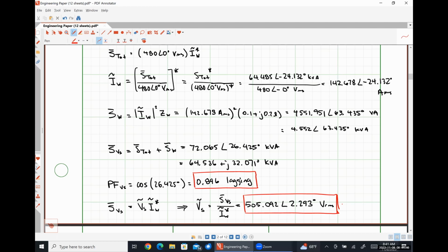So an electric utility prefers that we operate usually somewhere between 95 to 97.5% power factor, and this 89.6% is less than that, which means that as it stands with this particular load, the user would be fined some amount of money because we're effectively wasting the electric utility's resources. So what we're going to talk about now is the different options that we have in order to correct power factor or make it appear as if the power factor is at an acceptable level, and how to accomplish that.